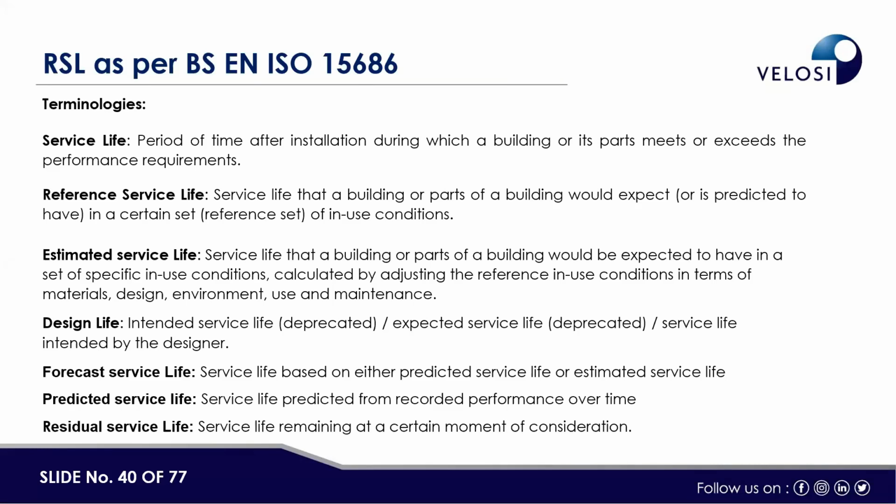So as per the code, there are certain terminologies that we need to follow. One is service life: the period of time after installation during which a building or its parts meets or exceeds the performance requirements. Then we have reference service life, estimated service life, design life, forecast service life, predicted service life, and residual service life. Reference service life is the life that a building or a part of a building would be expected or is predicted to have in a certain set of reference in-use conditions. That's reference service life.